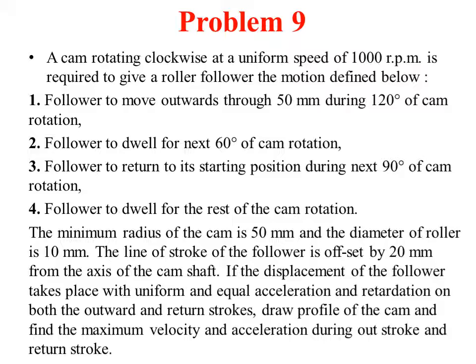Once that has been done, divide the angle AOS, that is the outstroke, into 6 even parts, same as the displacement diagram, and angle TOP, that is the return stroke, into the same number of equal parts, that is 6.